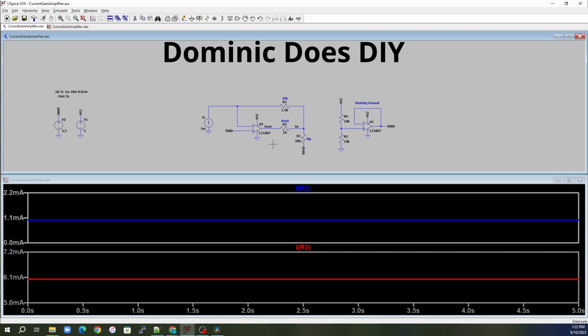Because our whole system, that's the system ground, so we can't go any lower than that. We don't have negative voltages. So that is our limiting factor. As soon as the op amp output voltage reaches 0 in the circuit, it starts to be unable to gain anymore. So now the question is, what is the limitation of this circuit?